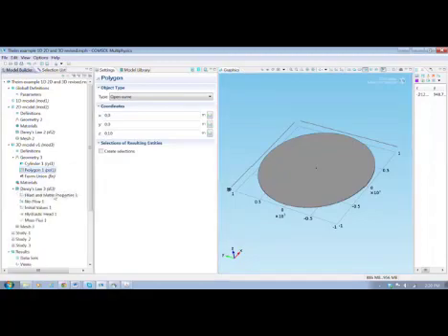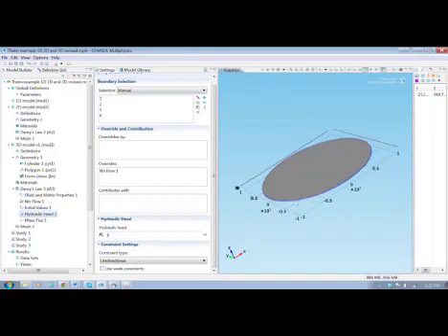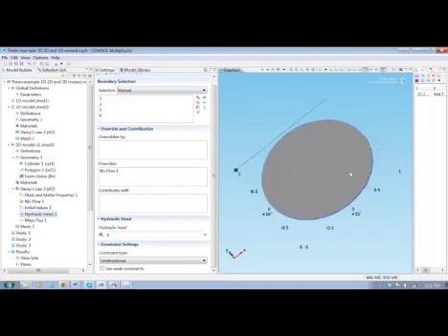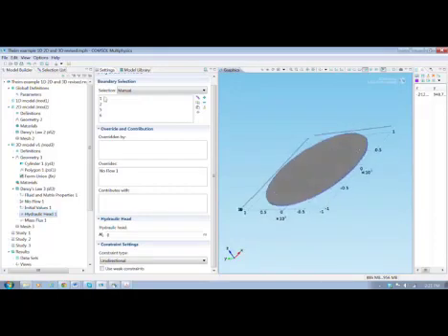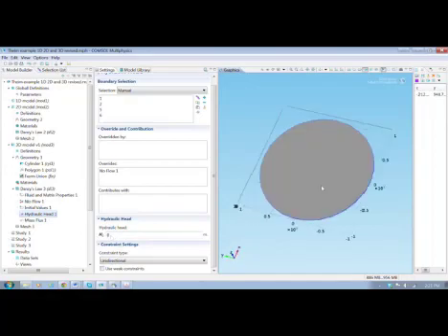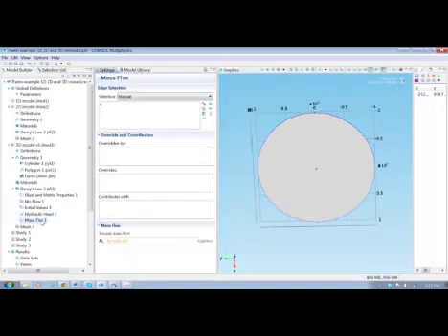So if we go to Darcy's law, we put this in just like last time. The hydraulic head around the outer edge is shown there. You can see that little purple band. There were 4 panels there, and all 4 were selected. They're shown here, and we select hydraulic head of 0. Now for the well here at the center, we used a boundary condition that's called a mass flux boundary condition. And so the mass flux was put in like this.